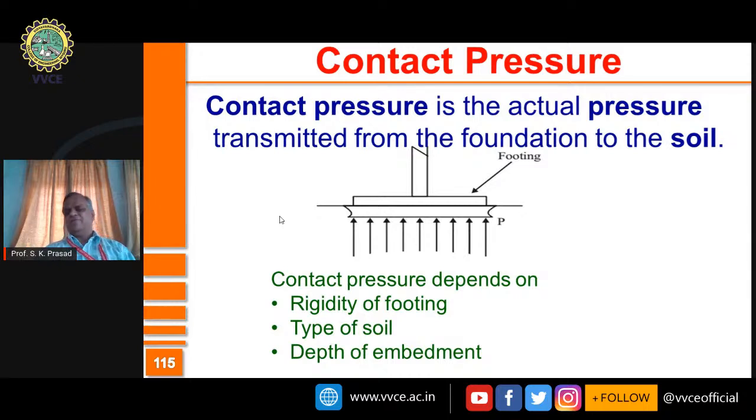Please note that we assume that contact pressure to be uniform in our design, or we may assume it to be varying uniformly. This is only for our convenience. So it's the actual pressure which is developed by the foundation soil at the base. And please note that it depends upon the rigidity of the footing, how flexible the footing is or how rigid the footing is, type of the soil, and then the depth of embedment.